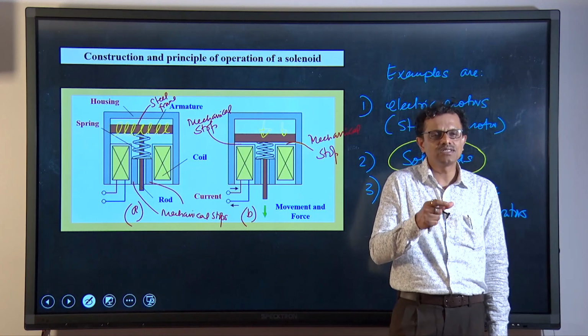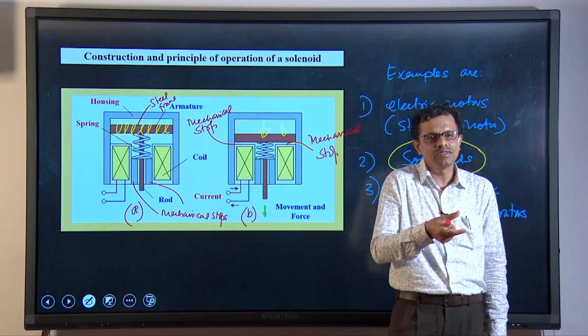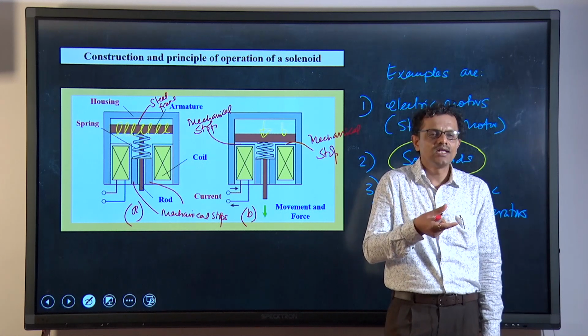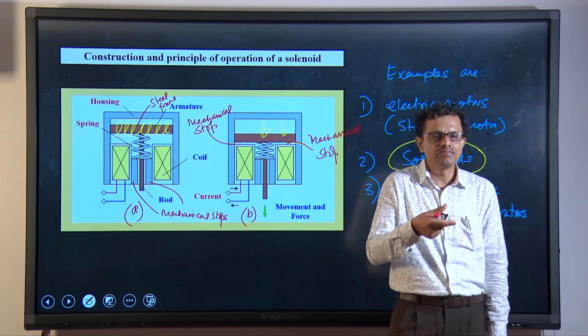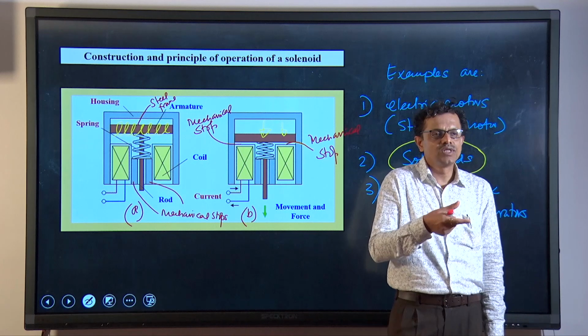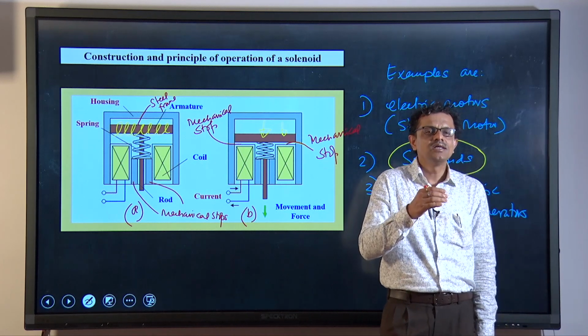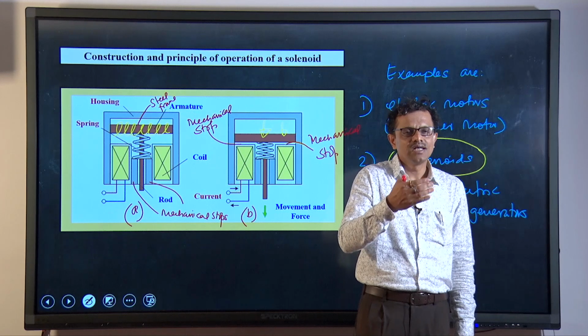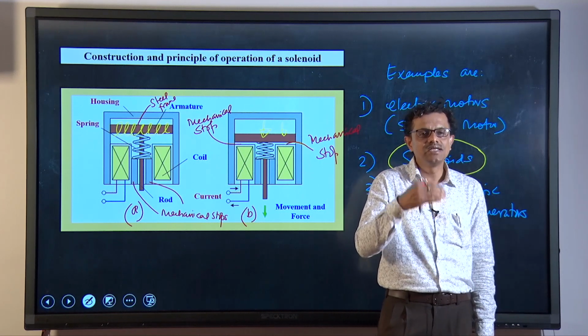By expanding piezo crystals and bringing them back, we can have some control, and if we connect another mechanism to the piezo crystals, then in tune with the expansion and compression of the crystals, that mechanism will also have some linear motion.